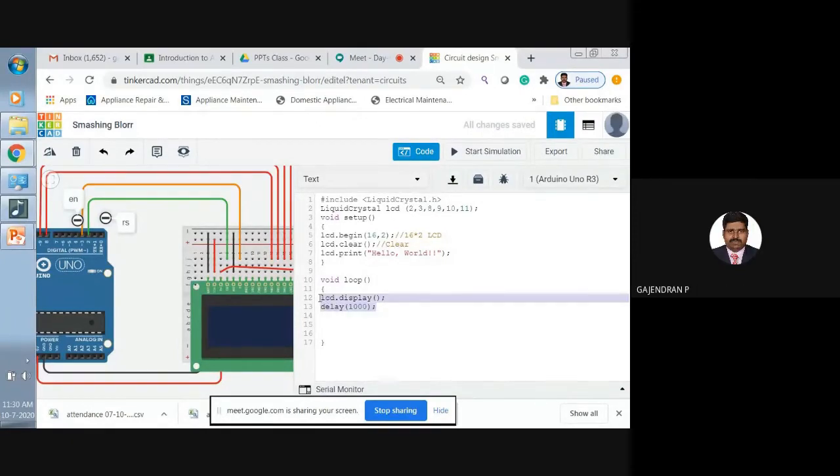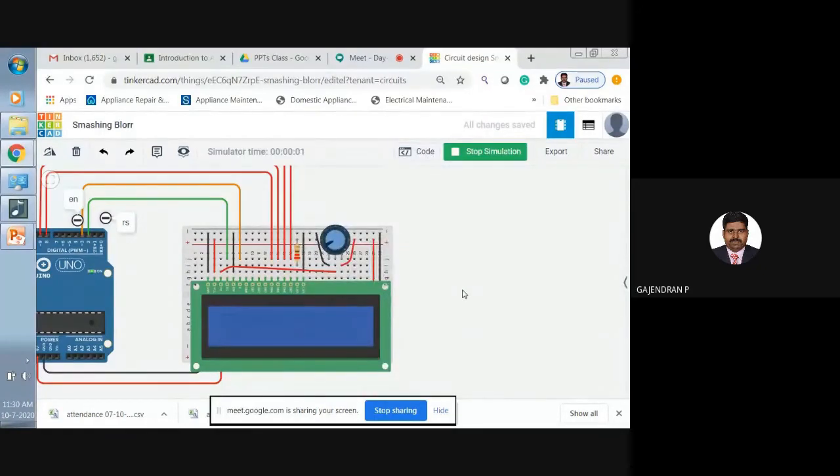See, the display is on for some time, off for some time. So simply noDisplay, this D must be a capital letter. Okay. To differentiate the on and off time, let me change the delay time. Now you see the hello world statement. Now I am going to make it on for some time, then off for some time. These are all very simple inbuilt functions. See, for 2 seconds, noDisplay. Only for 1 second, we will give the display.